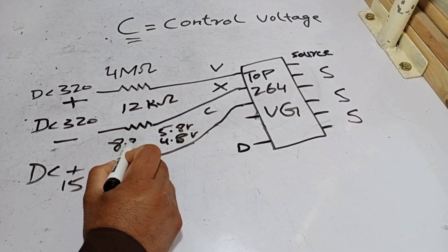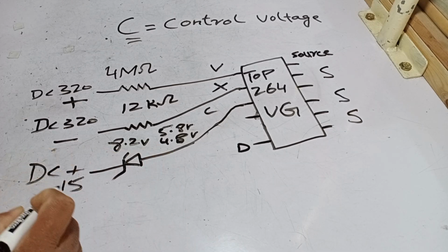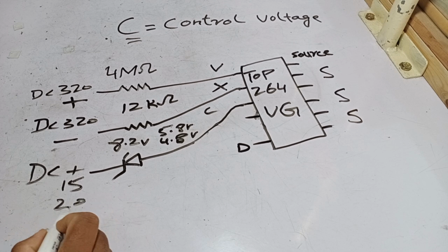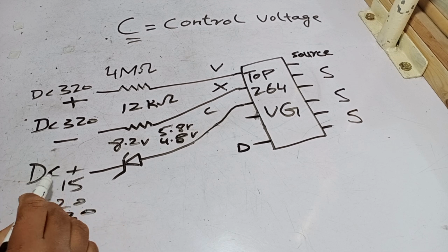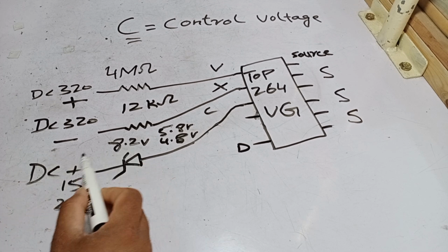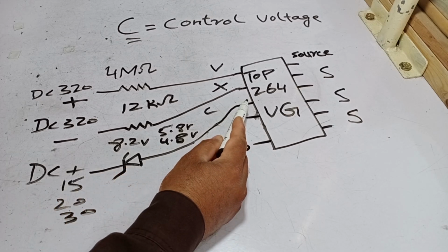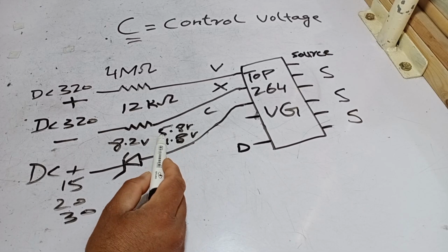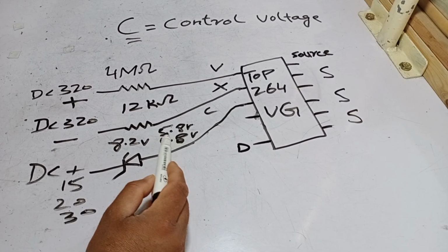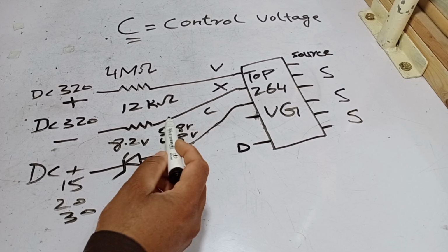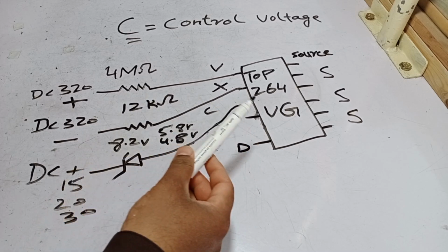This Zener diode is rated at 8.2 volts, which means that even if you supply 20 volts or 30 volts, it will only allow 8.2 volts to pass through, blocking anything above that. These 8.2 volts are then fed into the internal voltage regulator, which turns on and stabilizes the system. This ensures that the switching IC becomes stable and the entire system functions properly and efficiently.